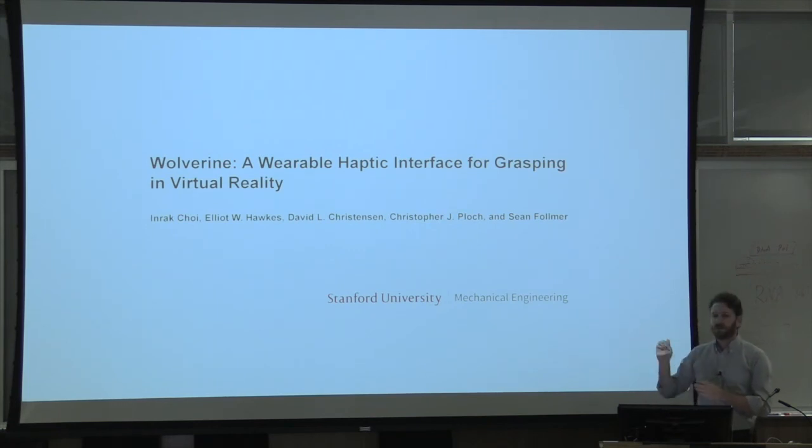So we use these one-directional brakes. As you apply force downward, the brake is on, but you can move your finger up and the brake doesn't affect it at all. So that reduces the stickiness. Also on the low power side, we just turn the brake on for something like 10 microseconds, and then your finger force downwards holds the brake in place the rest of the time. So it's really low power, low cost, so we can have a small battery and run for many hours.